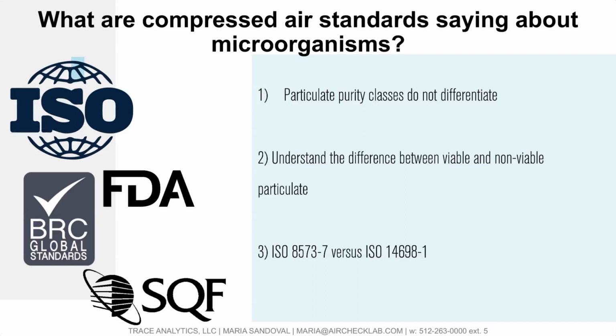We also have another ISO standard that talks about microorganisms in controlled environments, specifically in your compressed air. ISO 14698 is a standard that talks about biocontamination in controlled environments. For many of you who are doing ready-to-eat foods, or if you have a clean room in your food facility and you use compressed air, ISO 14698 is a great tool, but it doesn't tell you how to do the testing.